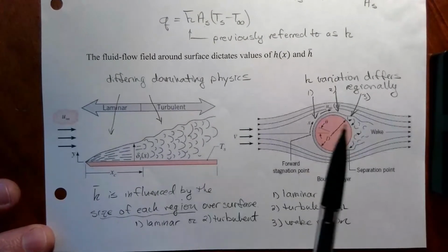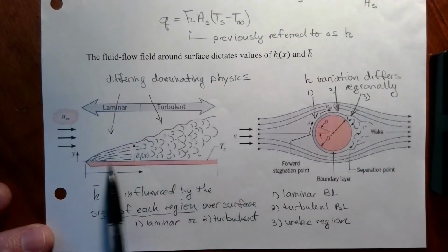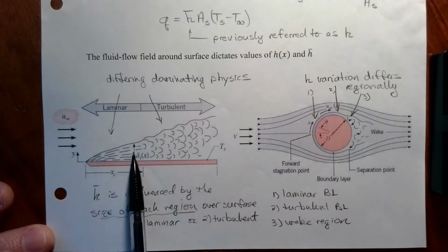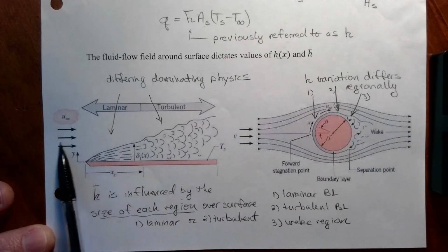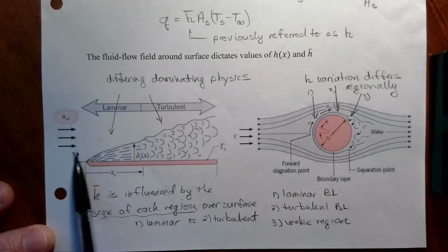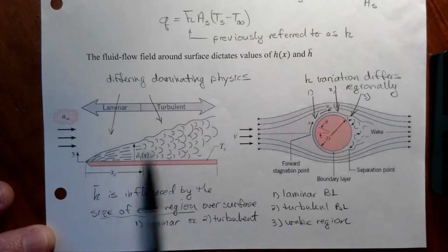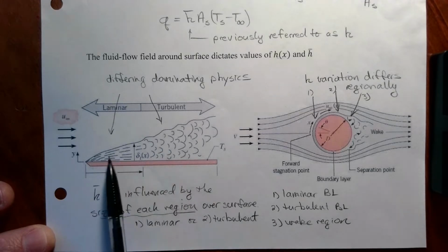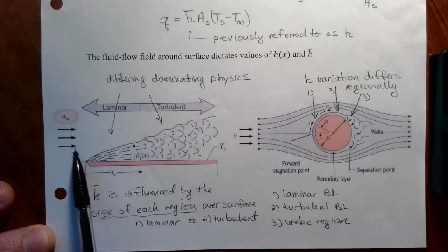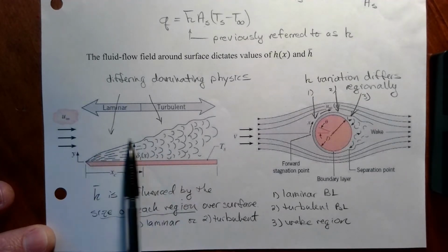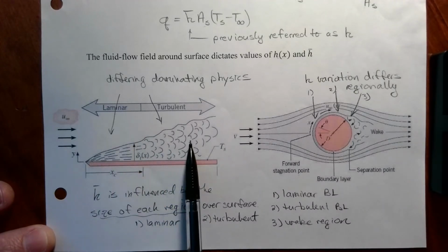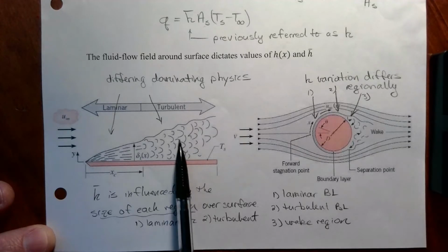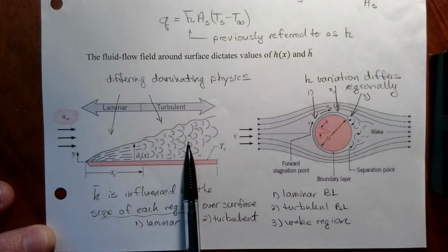For example, there will be a laminar region of flow near the leading edge of a flat plate, where if we had a uniform parallel flow coming in over this plate, that would be laminar for a while, and so streamlines are collinear and moving along in this direction, and at some point the flow becomes unstable and you get little vortices, little gushes of flow up, backwards, and around.